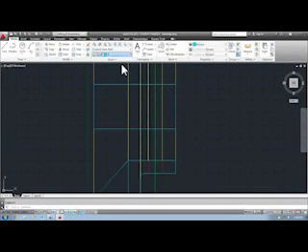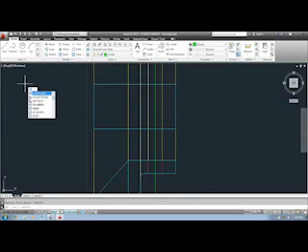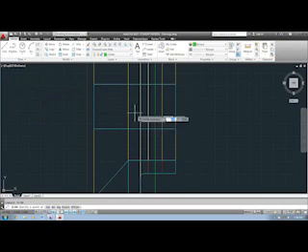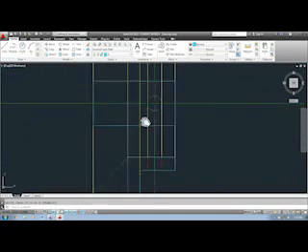Let's see. Going to go back to my center. And now I'll draw an X line, actually. Get this one. Okay, mark the midpoint. Okay, and where those two X lines intersect, I'm going to draw a circle that defines the hole right there.